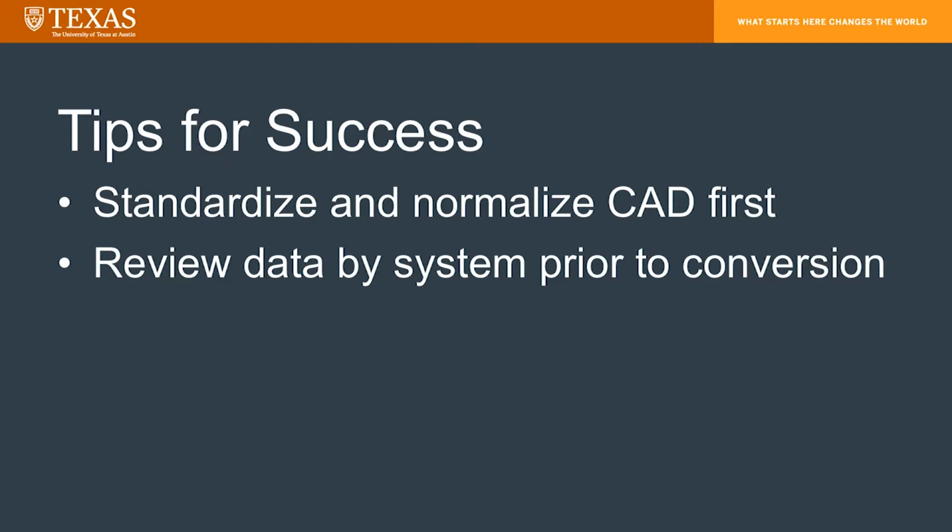So for future integration with projects, it's very important that you specify: text needs to be single line with insertion points, no MText in your AutoCAD deliverables. Objects need to be blocks with point insertions. All pipes need to be polylines, not closed polylines, and anything that represents a structure needs to be a closed polyline. That will facilitate moving forward as your utilities continue to grow.